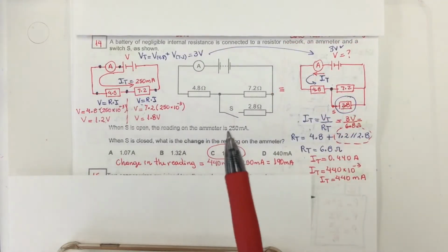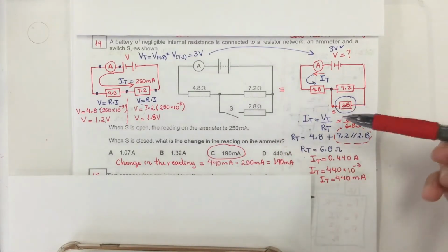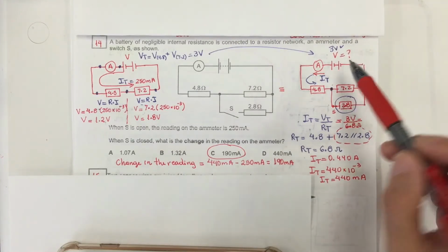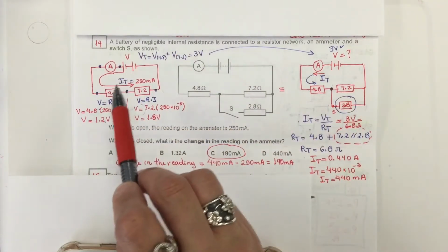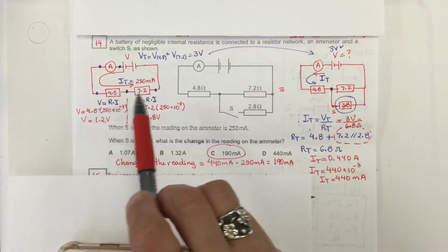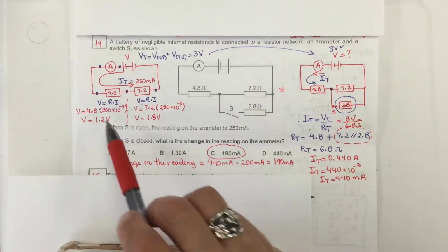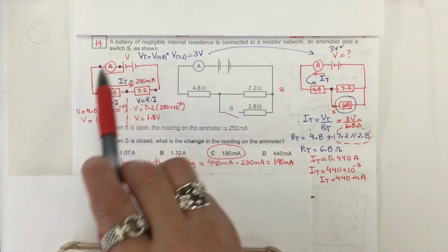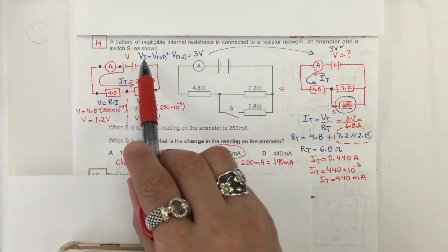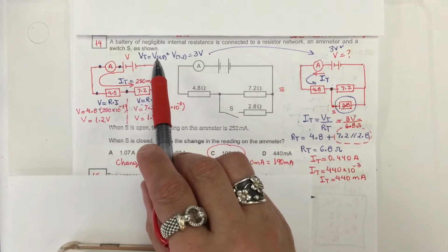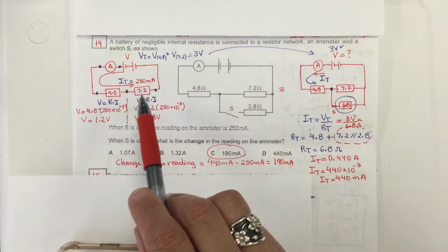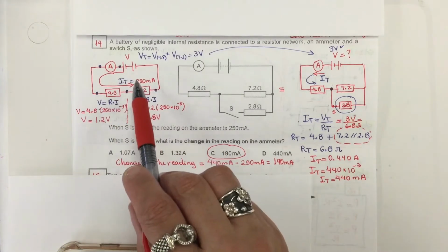This question definitely requires some of your skills to determine that missing factor, for example the voltage. You need to know that in series the voltage supply is equal to the sum of the voltage drops on each resistor in the series circuit.